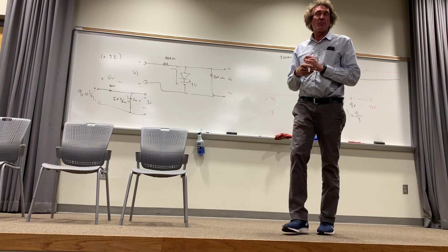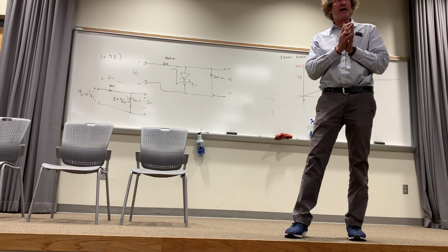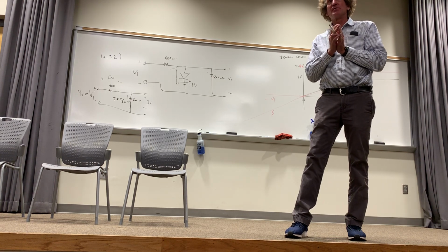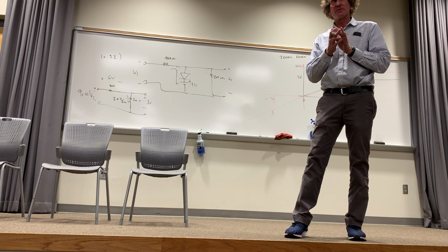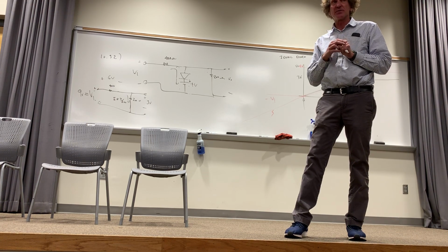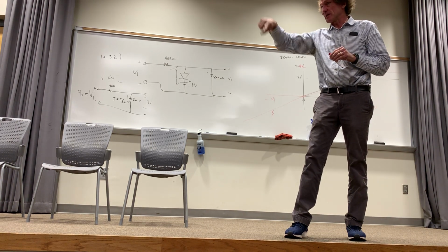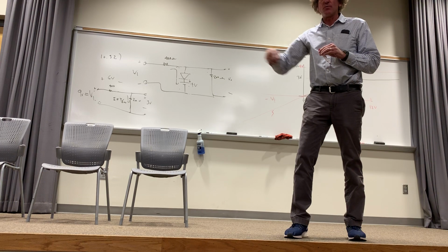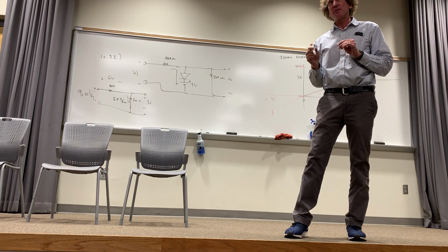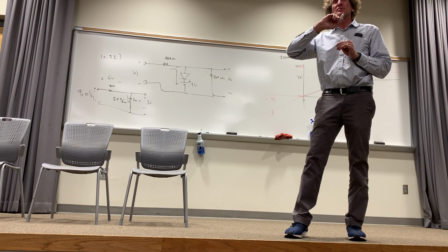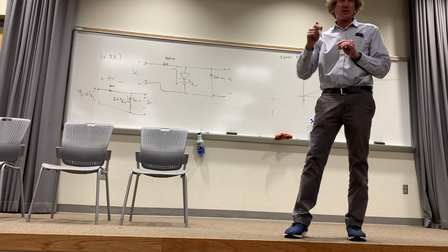I have done a lot of work where I had to create rectifiers that we talked about, full wave rectifiers. One time we had a 10,000 or 12,000 volt neon transformer that we had to build a full wave rectifier for using diodes. How many remember me talking about diodes being used to get DC? Just raise your hands. If you were here, you did. It took a cycle like this and made it all positive. It's called full wave rectification. Well, each one of those diodes at some point experienced a voltage that was the peak voltage, only it was in the inverse direction. And when that happens,